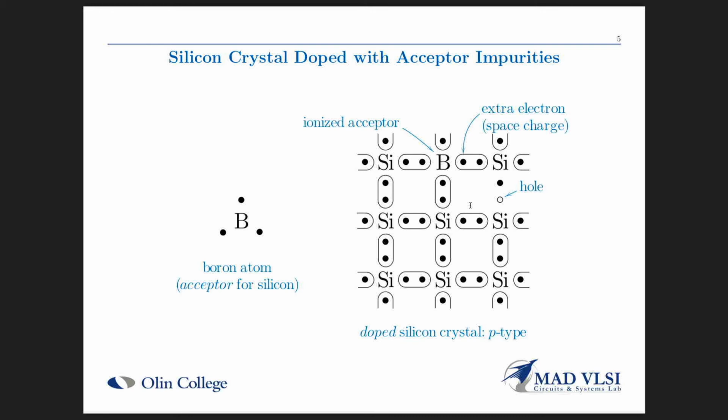And so it wouldn't be unusual to introduce dopants at, let's say, a concentration of something like 10 to the 17th per cubic centimeter, or 10 to the 18th per cubic centimeter. And that's 7 or 8 orders of magnitude more than the intrinsic silicon crystal's concentration of electrons or holes. And so the conductivity would be 7 or 8 orders of magnitude better than silicon that's intrinsic.